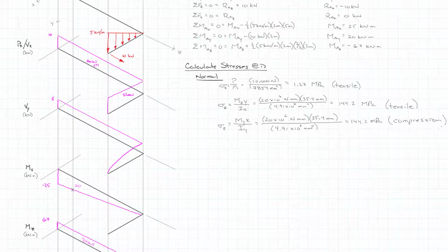So as far as transverse shear stresses, we have the one, which is our y direction. And so we're going to have a tau as a result of V in the y direction. So that's VQ over IT for transverse shear stresses, VQ over IT, that's V in the y direction. That'd be Q, I guess it's in the x direction at D, I sub x, and our thickness across that cross-section.